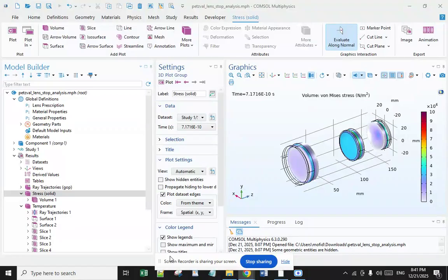And the structural analysis. With the thermal analysis complete, we can map the thermal results onto the structural finite element analysis mesh using ANSYS Mechanical. The structural deformation of both the overall satellite frame and, crucially, the mirrors in the optical payload can be computed.